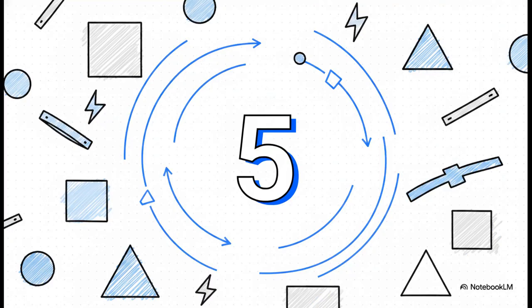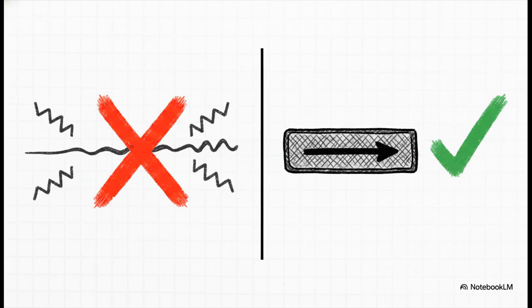Moving right along to Section 2, bonding for high frequencies. When it comes to the actual geometry of your bond straps, there is one massive, completely non-negotiable number you need to burn into your memory: 5. This is the famous 5-to-1 rule. Your bond straps must satisfy a 5-to-1 length-to-width ratio. Now, long, thin straps or simple little wires, they work perfectly fine for DC or standard 50 Hz power, but at radio frequencies, it's a completely different ballgame.